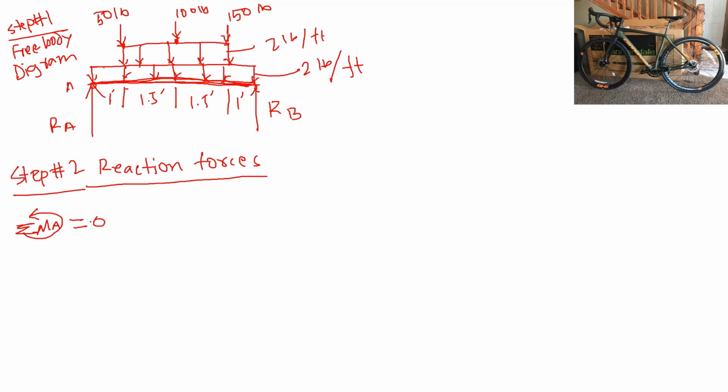We are only solving this problem for one snapshot of the bike ride. Assume that this is the distribution. Of course, we can change this load around. We can apply all the forces at the seat point, and we can solve for that. So this is an assumption of, say, at a random time this will be the loading situation on a bicycle.